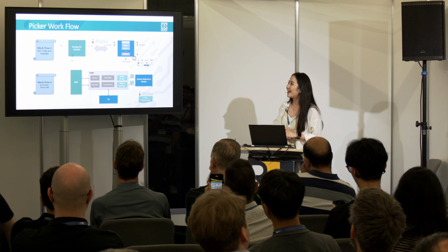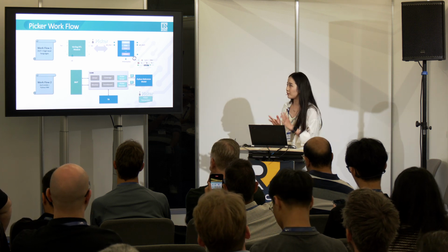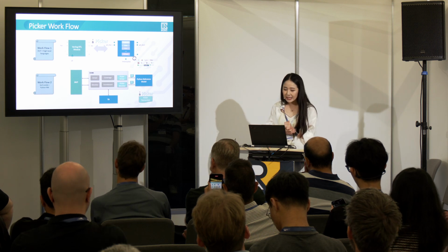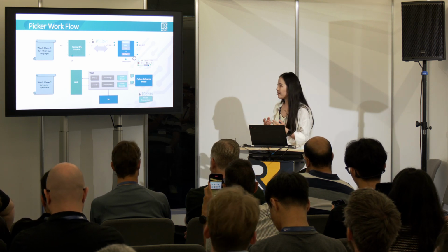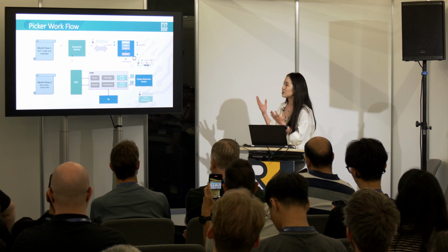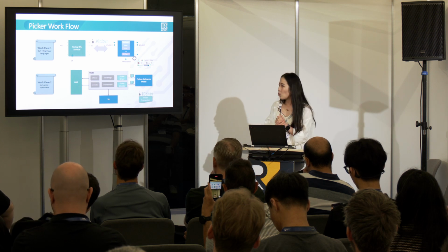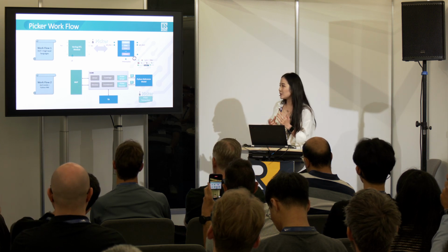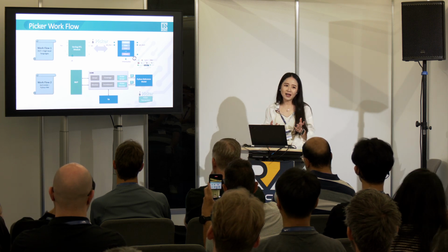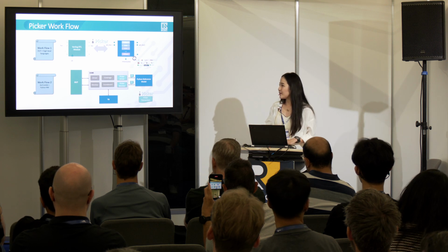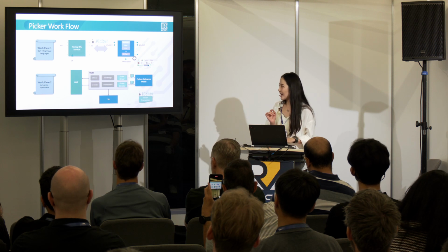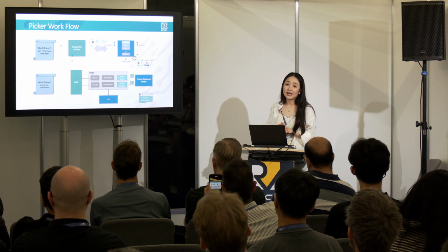So to summarize, there are 2 workflows in Picker. Workflow 1, you have your RTL DUT plus the high-level languages. Again, the RTL DUT is simply a software API, high-level API call in your software environment. Workflow 2, you have your RTL DUT plus UVM plus your Python reference model or even Python testbench. In this flow, it retains the UVM benefits as well as simplifies your reference model and TB into high-level languages.